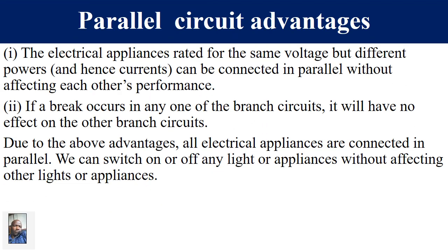Parallel circuit advantages. Please take note that this is important, and compare it to series circuit disadvantages. The first one is that electrical appliances with different ratings of voltage and currents can be connected in parallel without affecting each other's performance. This is a very important point. Then, if a break occurs in any branch, it will have no effect on the other branches.